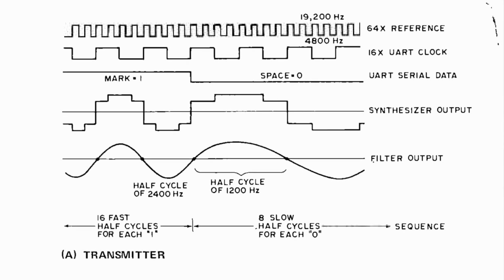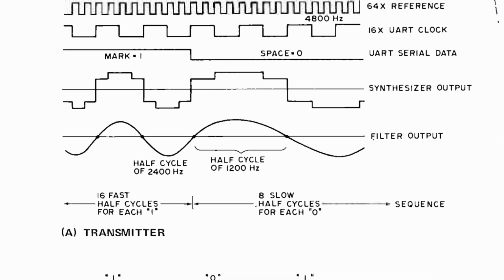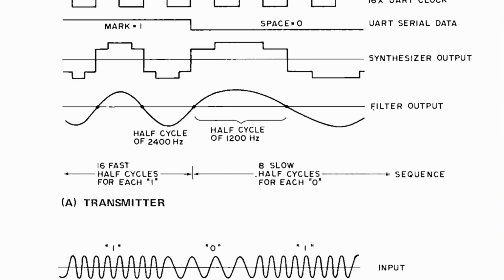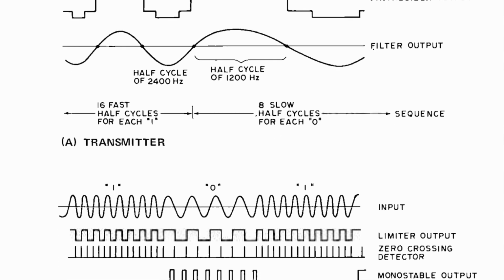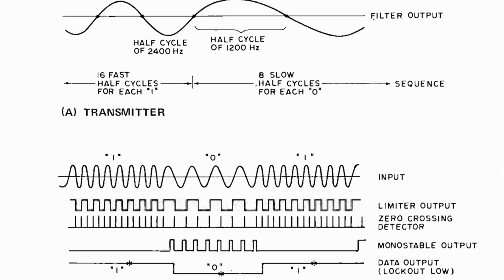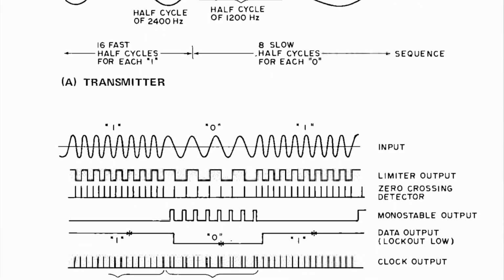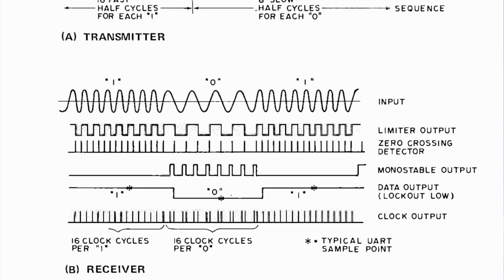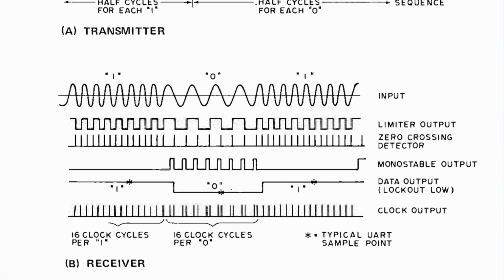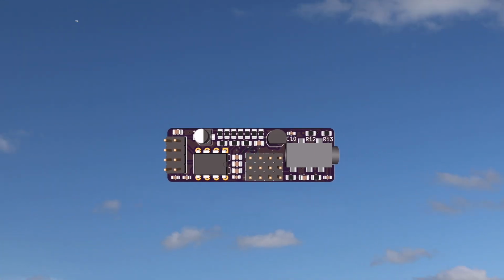Don's bit buffer is a bit too complicated for my taste because it assumes the input to be serial data along with a clock frequency reference of 64 times the baud rate and a serial clock of 16 times the baud rate. Instead of assuming everyone is going to use a 40-pin UART chip to interface with tape, I've gone with the assumption that everyone has some way of generating at least a square wave in software that'll be within a few percent of the two frequencies used.